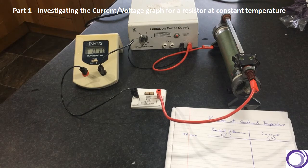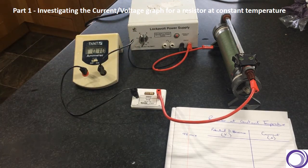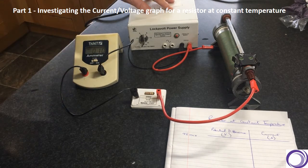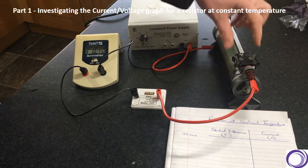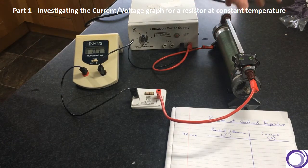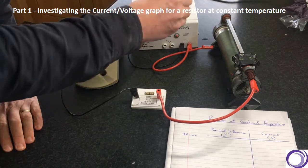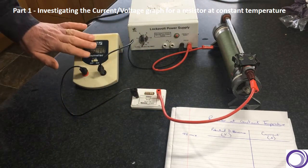I'm going to start off with resistor at constant temperature. The circuits are going to be the same for all 3 that we look at. Power pack, out from the power pack into variable resistor. I can change the value of the resistance by sliding that along. That'll mean that I can have different potential differences across the resistor. Series circuit, round through the resistor, back through an ammeter, so I can measure the current.